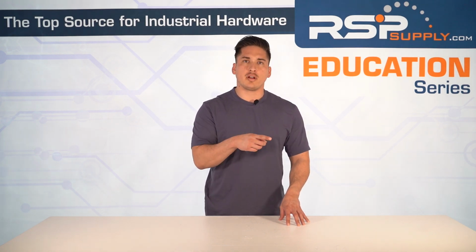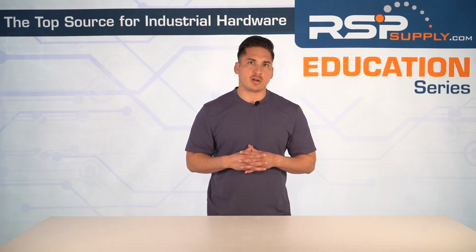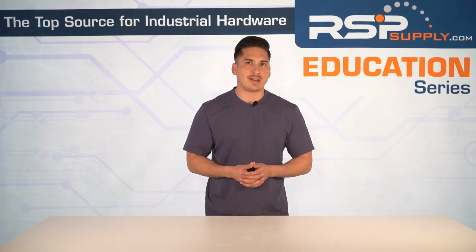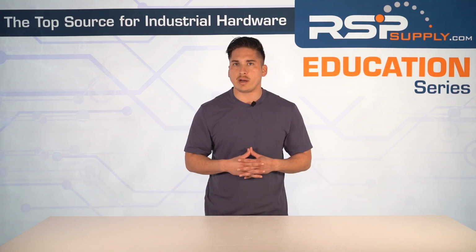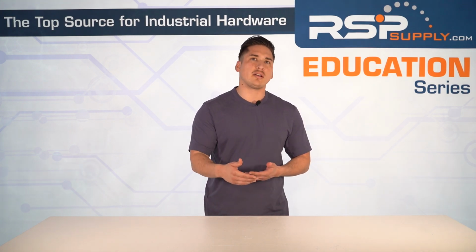Industrial Ethernet versus field bus. Industrial Ethernet is the backbone of modern industrial networks. It's fast, it's scalable, and it integrates seamlessly with enterprise IT systems. Protocols like Ethernet IP or Modbus TCP run on standard Ethernet hardware, cabling, switches, routers, and they're hardened for real-time control in factory conditions.